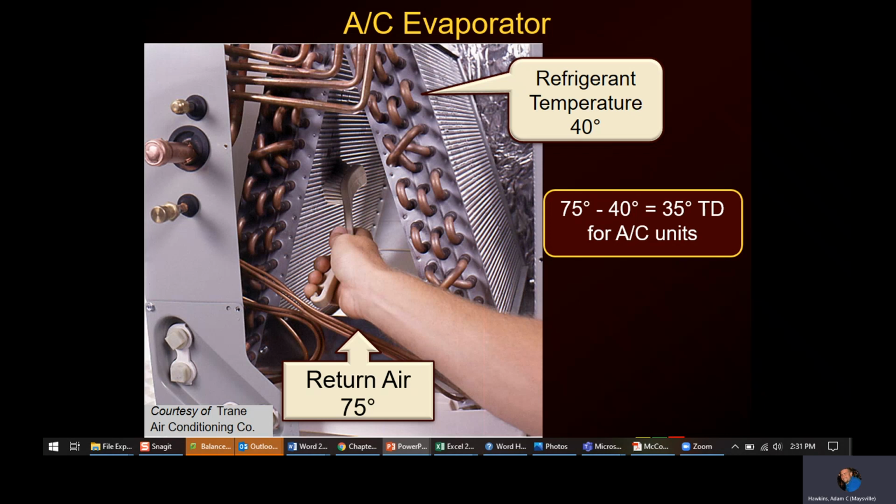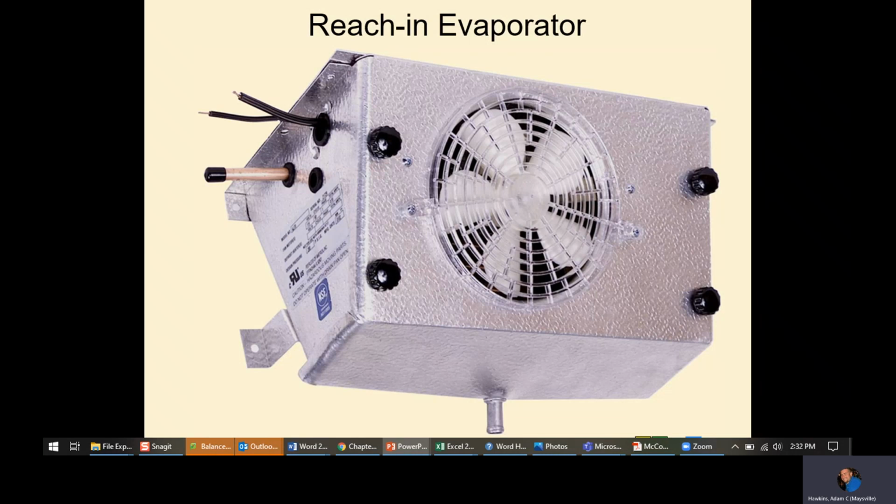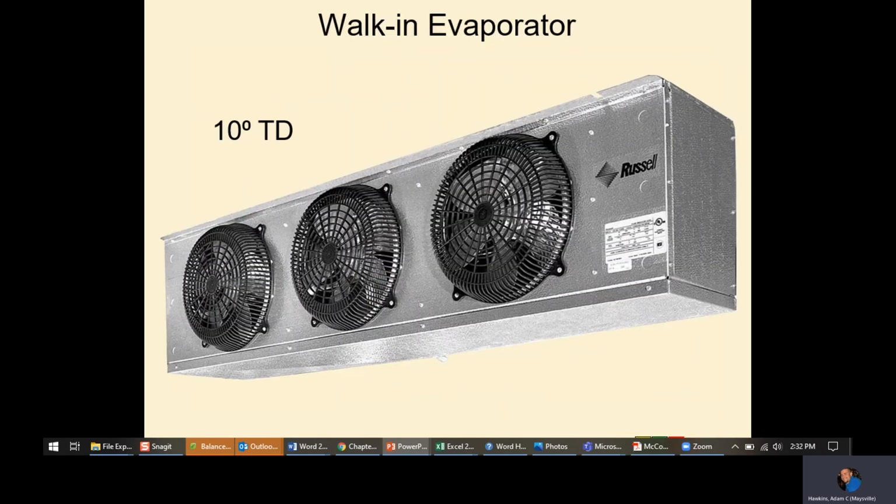That's not something you want to do if you can avoid it at all, because then you've got to pump your system down, cut your line sets, pull your coil, go outside, put cleaner on it, water hose, use an acid or some sort of high-powered cleaner, solder it back in, pull a vacuum. So you're talking about a pretty big process. So maintenance is a big deal. Filters is a big deal.